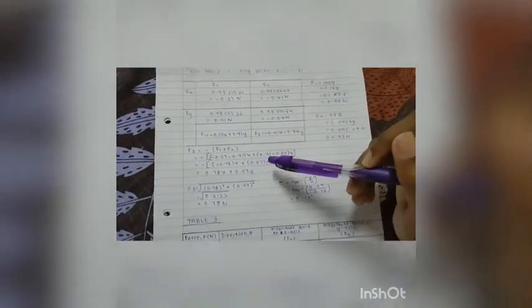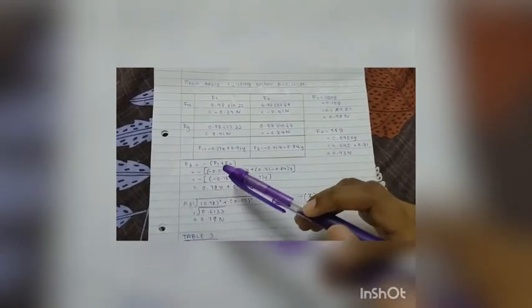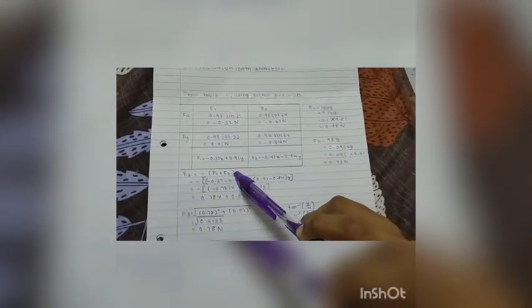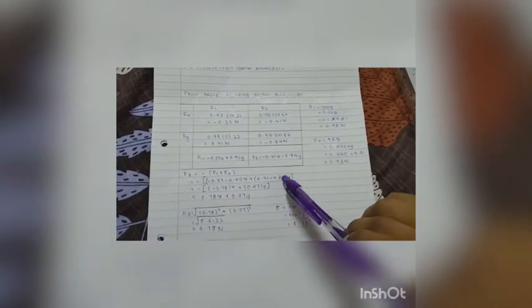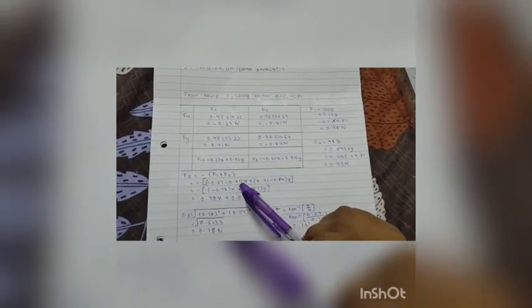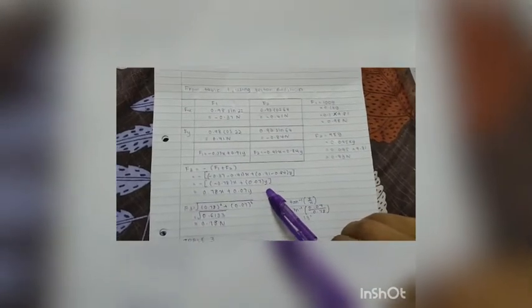So for force 3, we need to find negative bracket, and inside the bracket, we insert the calculation of force 1 plus force 2. I separate the force 1 and force 2 x components here, and the y components here. So negative 0.37 minus negative 0.41, you will get negative 0.78. Then positive 0.91 minus 0.84, negative 0.84, you will get 0.07. So this is the value.